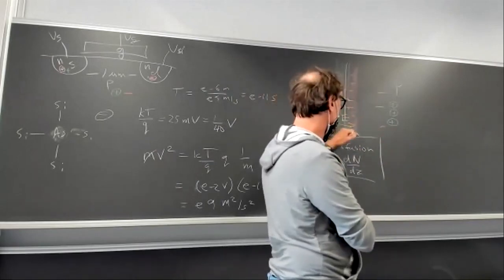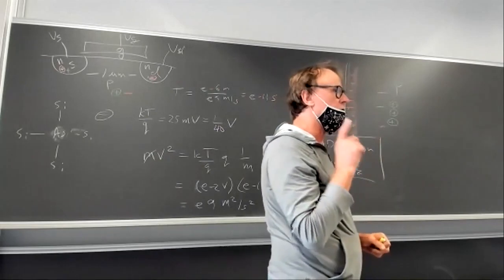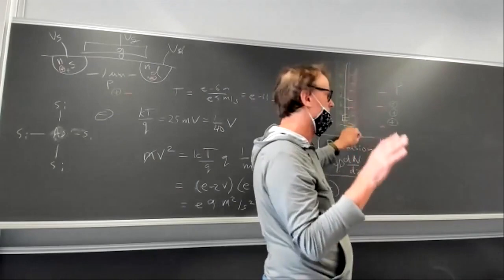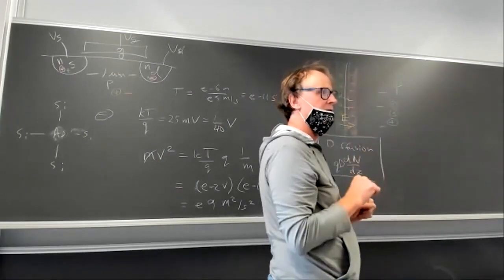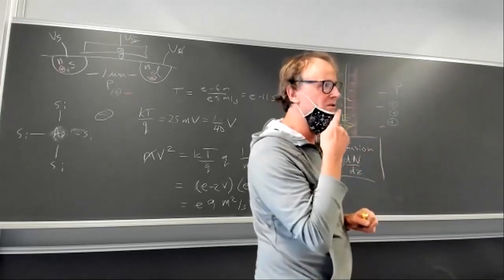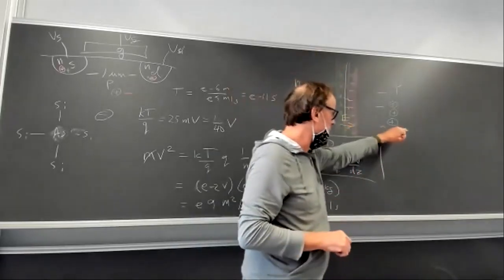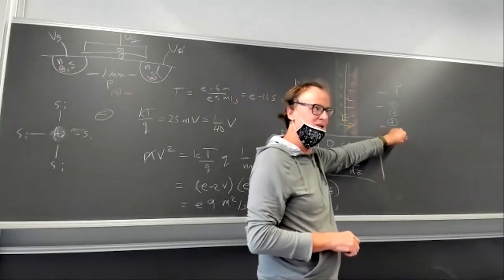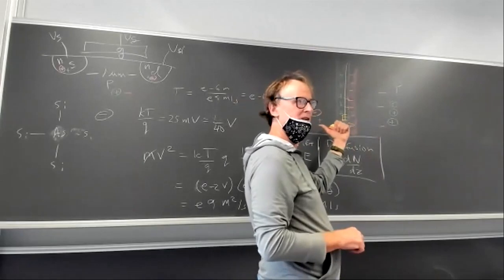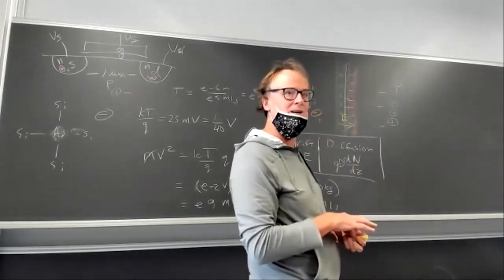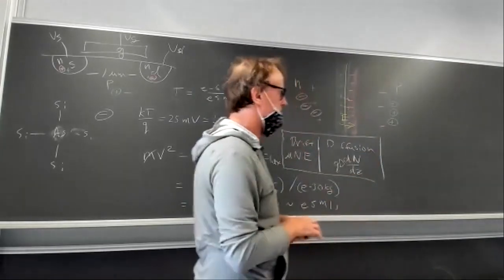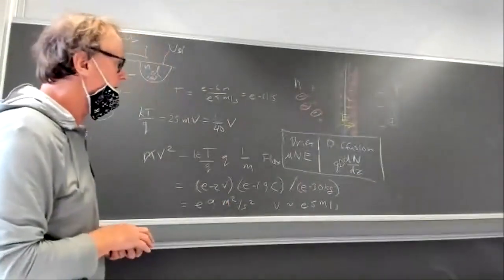And we know the electric field always pulls carriers home. The built-in electric field that builds up between oppositely doped regions makes carriers go home. You can remember that if you're ever confused about it. It pulls the holes back home to the original p-type region, and it pulls the electrons home to the n-type region. It opposes the diffusion current. Is it clear? It must, because there can be no net current.